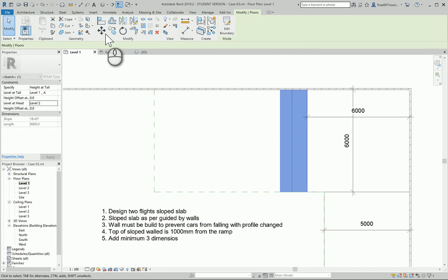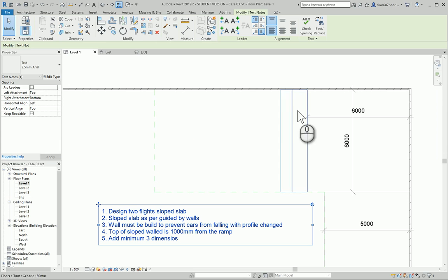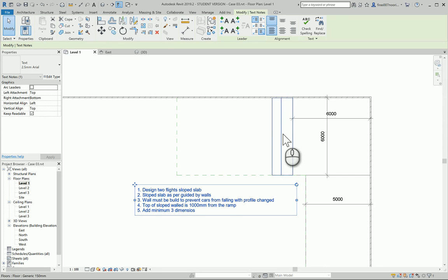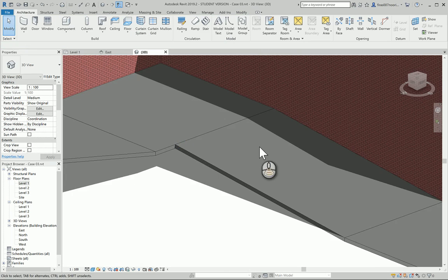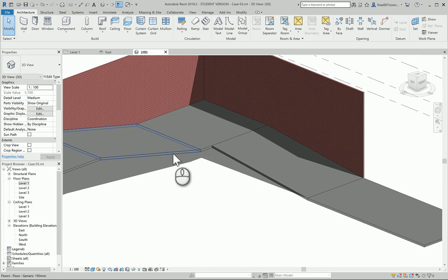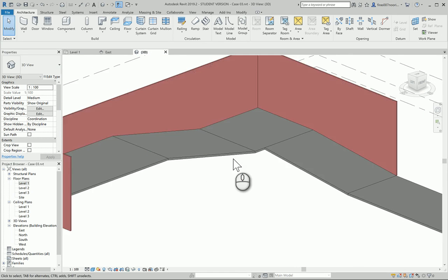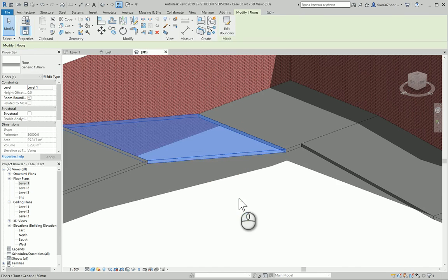It's very easy. You might see this as a cutoff. It is okay because it's like a 1.1 or 1.2 millimeter cut section, and it's higher than a specific level where it cuts the geometry in the middle. Don't freak out, just go to 3D and you're going to see it properly. The plan at that level cuts it around 1.2 or 1.1 from the 0, which is somewhere here. That's why you don't see the rest of it. But as a mass, it's perfectly laid out, as you can see.